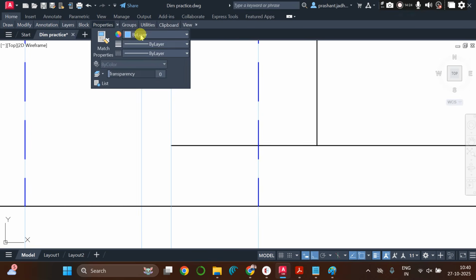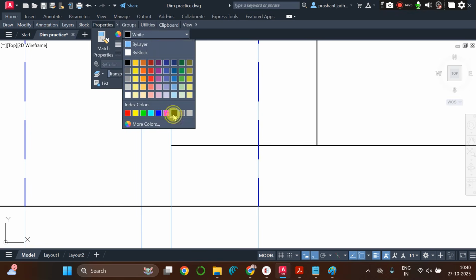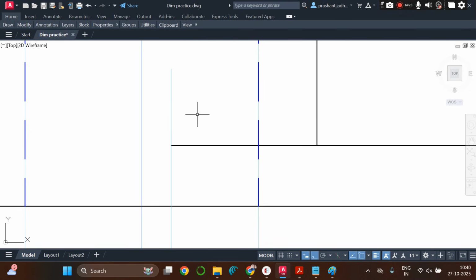First I will set my layer as a visible layer. Okay. Now see, the procedure for fillet is F, enter, T, enter, N, enter, R, enter. This is F, T, N, R. Now it is asking me fillet radius. So here you want to set a very small fillet radius, around 3 mm. So I will select 3, enter. Then select this object and this object.